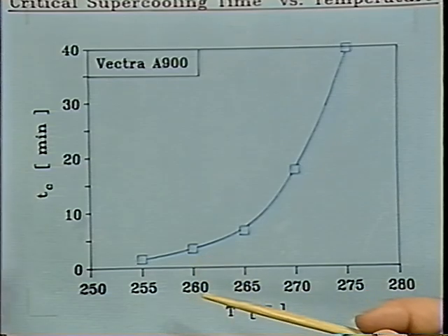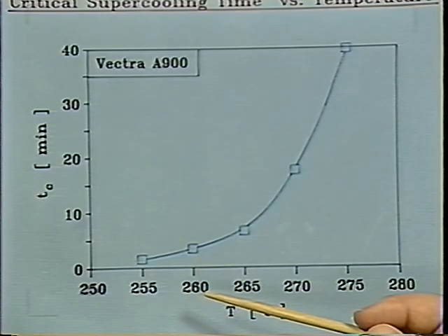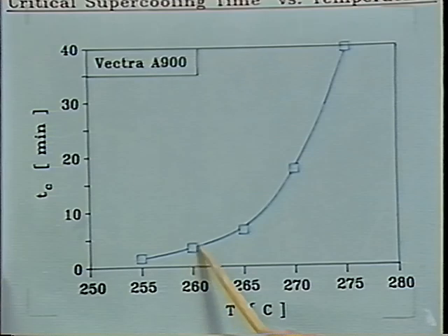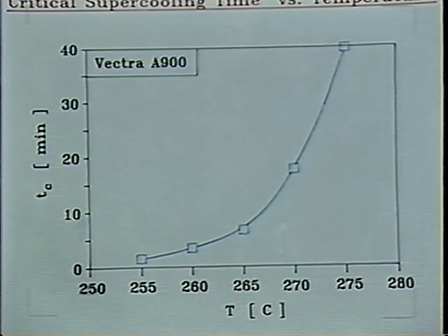During that time, we could blow films or blow bottles and make something out of the shaped melt and quench in the flow-induced structure. So processing in the supercooled state with this type of rheological experiment will be very successful, and we will know the time scale. We can tailor the time scale by changing the chemistry and doing rheology in an experiment like that.